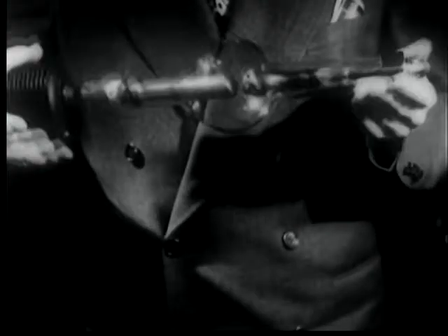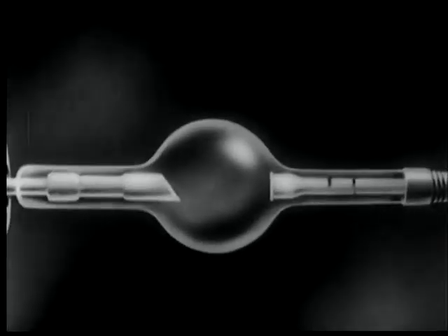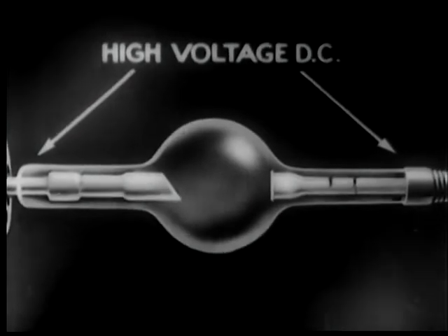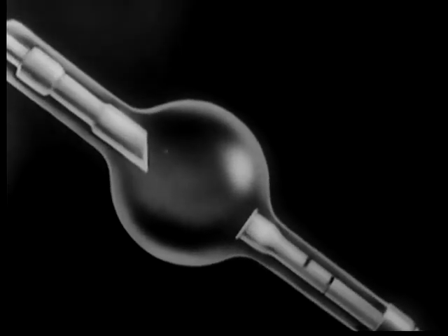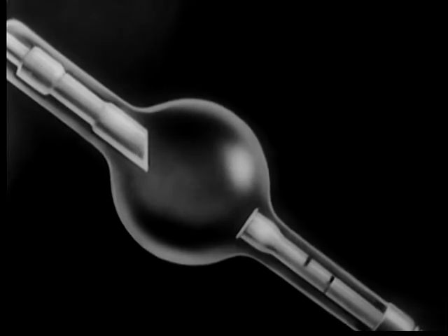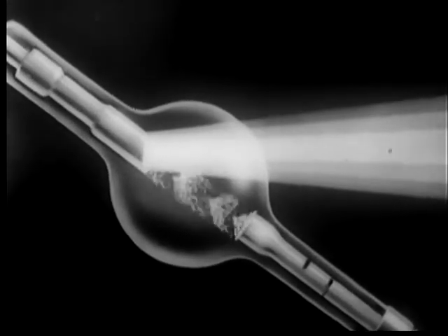The electronic X-ray tube indirectly also transforms electric current into light, and by its effect on photographic plate, into light images. Here's how an X-ray tube works. A high potential ranging up to 300,000 volts or more is applied between the anode and cathode. Electrons are emitted by a focusing cathode. Due to the extremely high voltage, the electrons hit the anode with tremendous impact and cause the emission of waves of exceptionally high frequency.